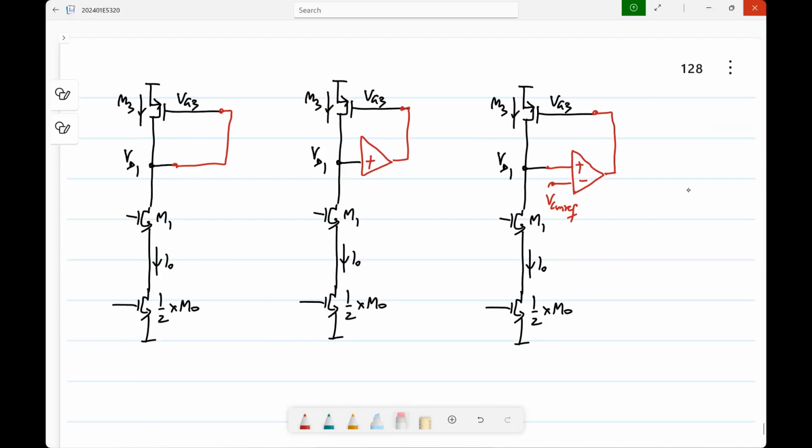Now please think about how to combine these with the differential circuit. And what is the principle to use? Again, in the differential half circuit, the line of symmetry will be at 0 volts and so on. That is what you would have to use to combine these. This is somewhat similar to earlier, when we had different biasing techniques and different amplifier functionalities, the incremental pictures, and you combine the two. Of course, we were using AC coupling heavily at that time. Now we won't use that. Please think about that.